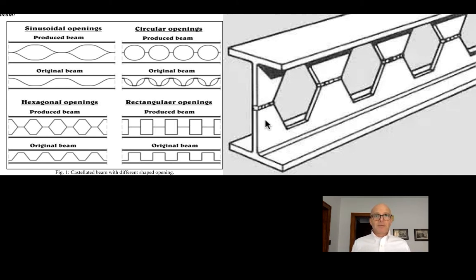It has cost us something in terms of fabrication, but we can, of course, set this up on a plasma cutter. We can do robot welding. We can do this relatively easily. And now we have really a hacked beam. What had been a 6-inch W shape is now an 8-inch W shape. It has a higher section modulus because the flanges are further from the neutral axis, but it has exactly the same weight as the earlier beam.